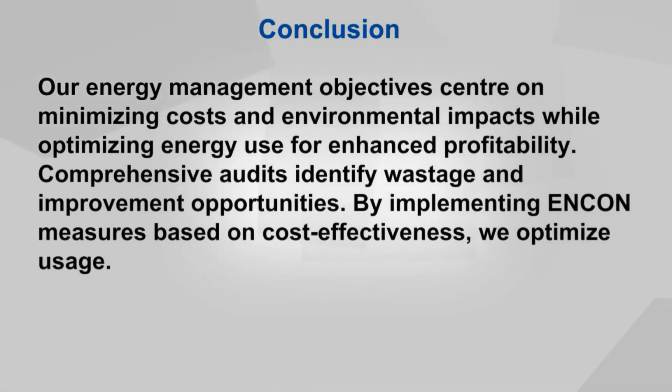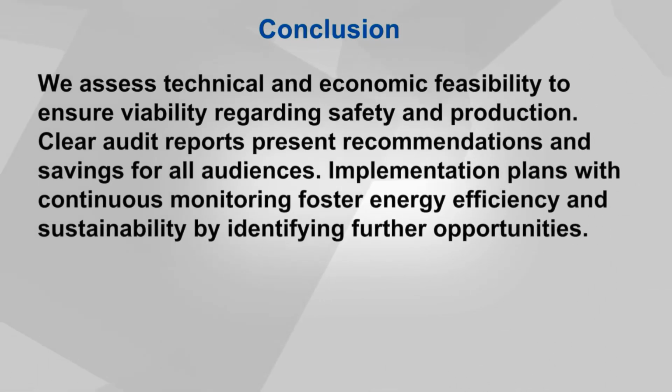These measures can be categorized into several key areas: reducing the heating demand by implementing insulation and utilizing energy efficient heating systems to lower the energy demand; reducing cooling demand by deploying strategies like use of reflective material and integrating natural ventilation systems to decrease reliance on HVAC systems; reducing energy use for lighting by use of LED and automation systems and maximizing natural daylight; reducing energy used for heating water by deploying solar water heating systems; reducing equipment and appliances electricity consumption.